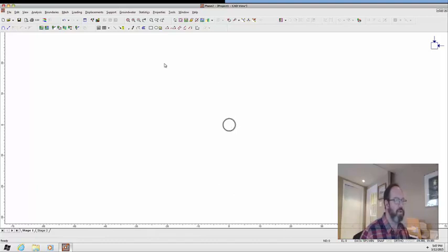The next thing I'm going to do is add the external boundary of the model. The external boundary defines the full extent of the modeling region. You want to have the model extents far enough away from your excavation that you're not going to have boundary effects. In other words, the boundary is not going to change your answer based on how far away it is. A good rule of thumb is that you want your boundary to be 5 to 10 tunnel diameters away from the tunnel.